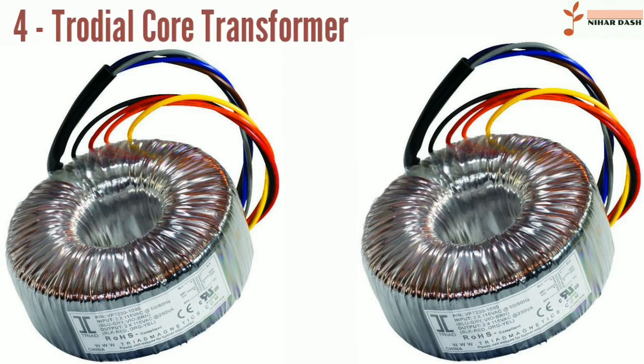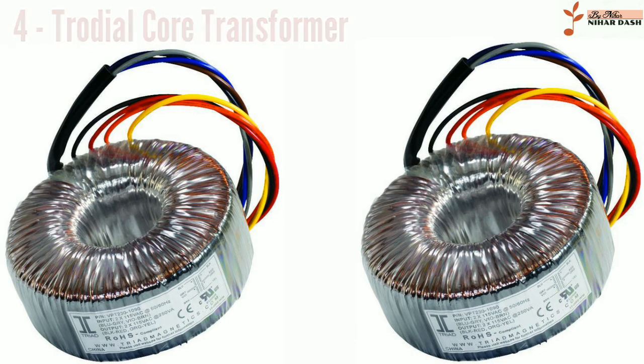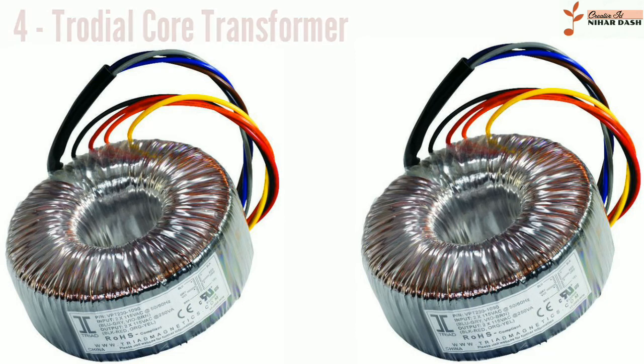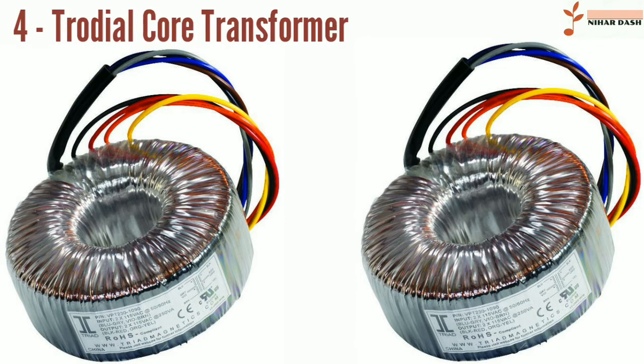See classification parameters below. Because of the lack of a residual gap in the magnetic path, toroidal transformers also tend to exhibit higher inrush current compared to laminated EI types. Ferrite toroidal cores are used at higher frequencies, typically between a few tens of kilohertz to hundreds of megahertz, to reduce losses, physical size, and weight of inductive components.